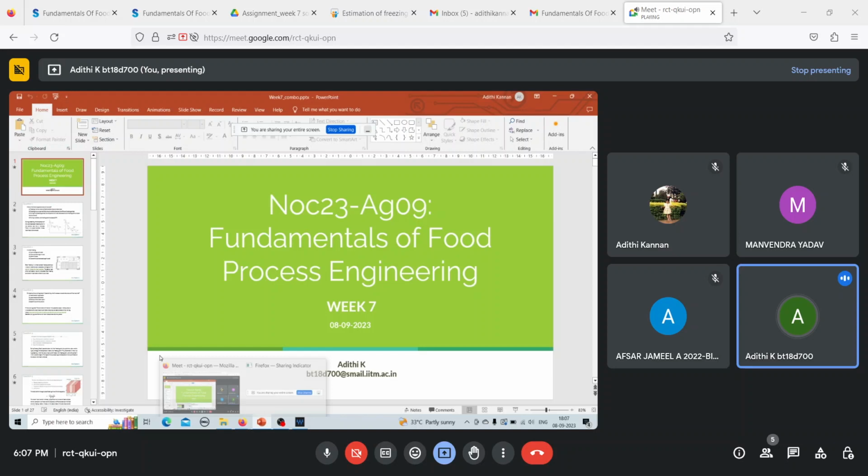When I substitute A as 0.025, my freezing time is now 3486.8 seconds, which is equal to 0.9 hours. The answer to this question is option C. So you can see very clearly that if you reduce the dimension of your food, then your freezing time also drastically reduces. The smaller the food particle you expose, the quicker the freezing process.